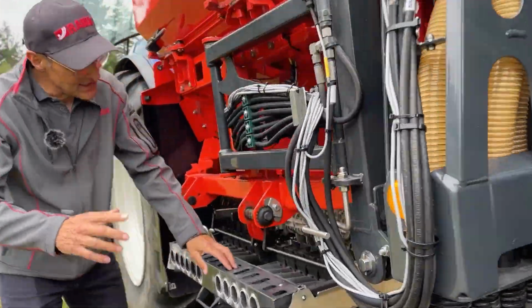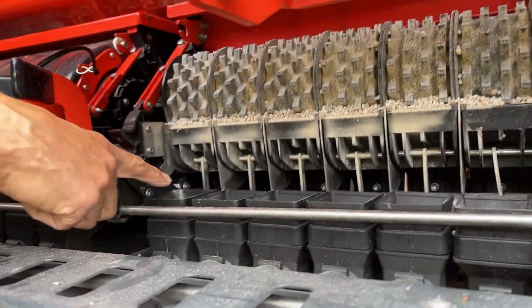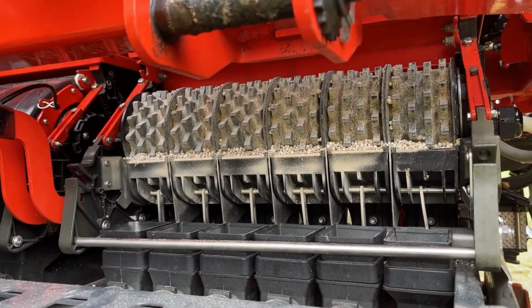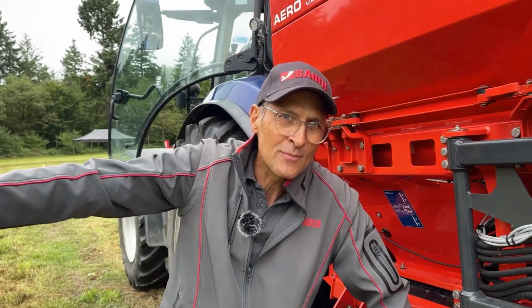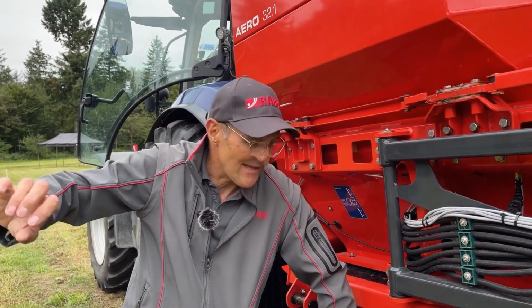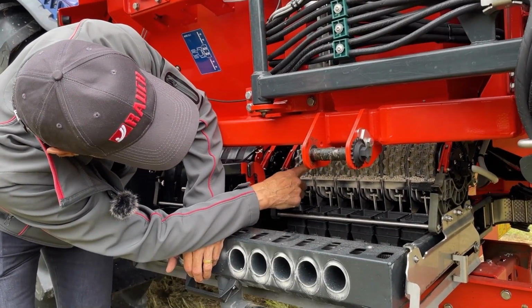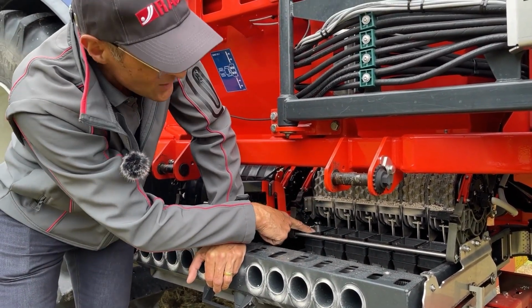If you look at the side here, it works like this. The injectors are down here. That's where the air comes out from inside, from the blower. And then it flows, or rather streams, into the boom. And here, via these cam wheels that rotate, the fertilizer is metered into the airstream.